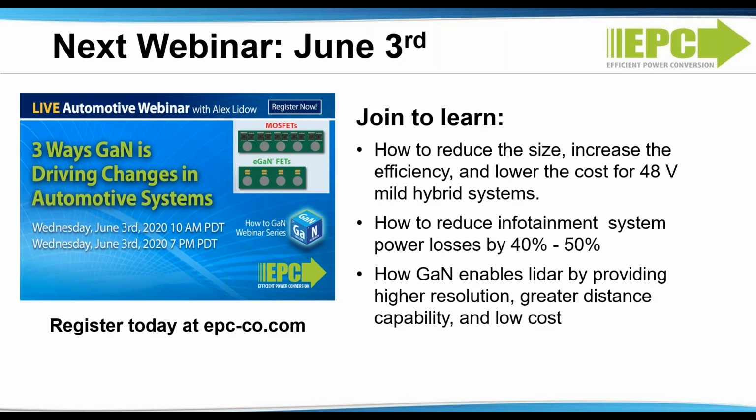Now, in the early days, that was a bit of a problem because people had to roll their own drivers out of discrete components, and it was a little bit harder to get a good layout. So we had to work really hard to stay inside the 6 volts. But nowadays, with all the driver ICs available, they already have over voltage protection for the gates of our devices, so they never go over 6 volts. So A, they are robust, B, we rate them more stringently than MOSFETs, and C, the ICs that you're going to wind up using for gate drivers will take care of it anyway.